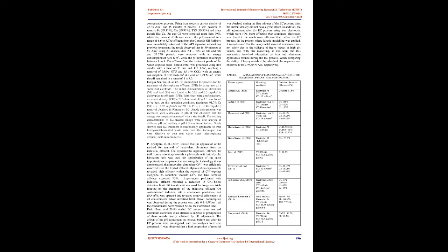The results showed that the removal efficiency of heavy metal ions increases with increasing both EC residence time and direct current density. Over 97% of heavy metal ions were removed efficiently by conducting the EC treatment at current density, CD, of 4 mA/cm2, pH of 9.56 and EC time of 45 minutes. These operating conditions led to specific energy consumption and amount of dissolved electrodes of around 6.25 kWh/m3 and 1.31 kg/m3, respectively.